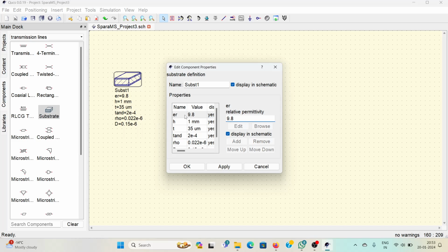So let's go ahead and set this microstrip line on an FR4 substrate, because that's the most commonly used substrate. It's low cost, widely available, and easily available. The values that I'm taking for FR4 can vary a lot. The relative permittivity varies from maybe 4.2 to 4.8.